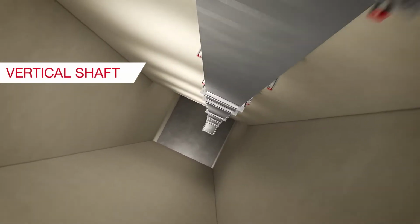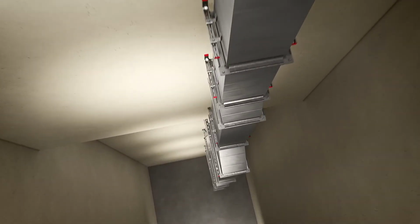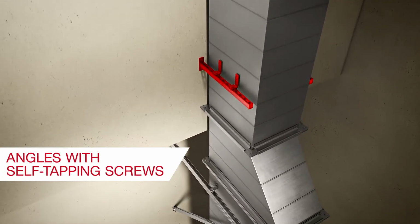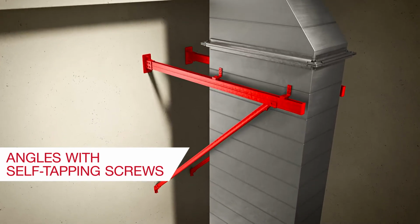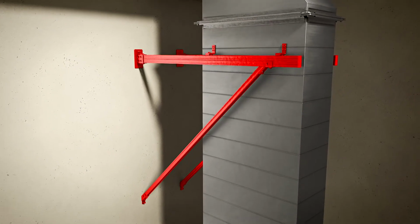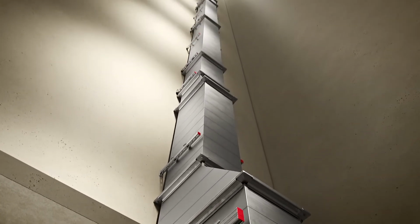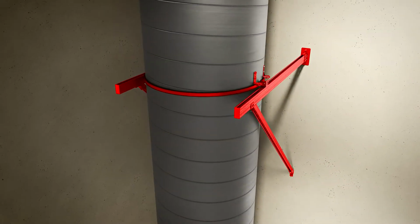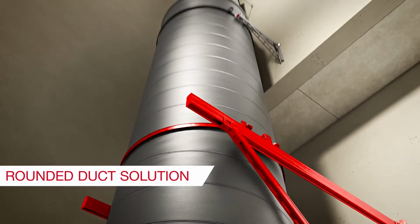From the plant room, the air duct system typically ascends or descends through vertical shafts. In the case of rectangular ducts, angles with self-tapping screws can be used to transfer the loads onto the brackets. Alternatively, the load may also be transferred by resting air duct connection flanges on top of the brackets. Rounded ducts require a similar solution, most notably for bigger dimensions.